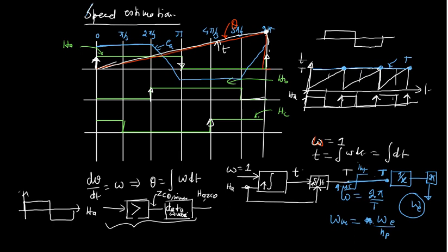So this is one of the methods we have done. If you want to make it more reliable, you can do the same with all the other phases also, and you can update your speed after each 120 degrees. Like here the calculation is done. Previously you used this calculation for Hall C. Then after again 120 degrees you can update it like this. So this is your algorithm, but I'm just explaining it with one of the phases.